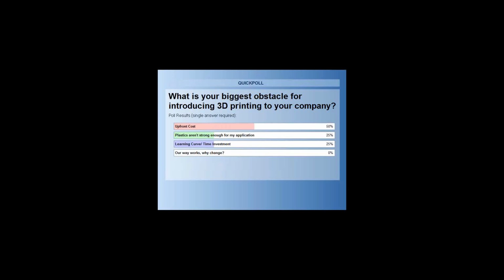Hey, Jeremy, is there a whole new way of designing if you're going to 3D print, or is it just a slight modification to your part, or do you even need to change your model at all? Well, the short answer is it depends. It depends on how you want to use your printer. If you want to get the most out of it, yeah, we would want to change the design a little bit. So all those weird angles we would put in, like all the draft we'd put into injection molding to make it injection moldable, we could get rid of all that, make the walls straight up and down. We have stuff called self-supporting angle where we don't need the support structure. We can kind of trick it and not use it.